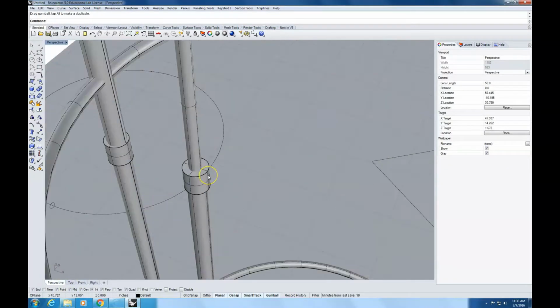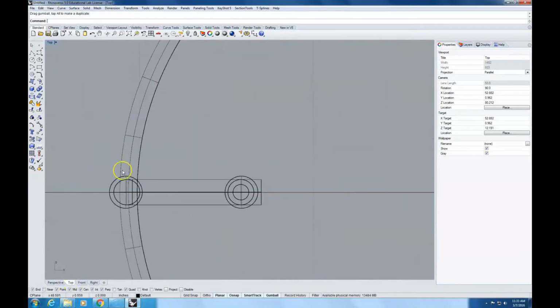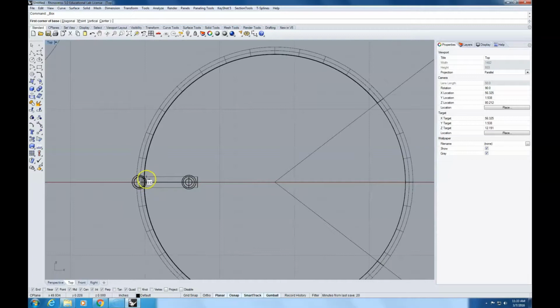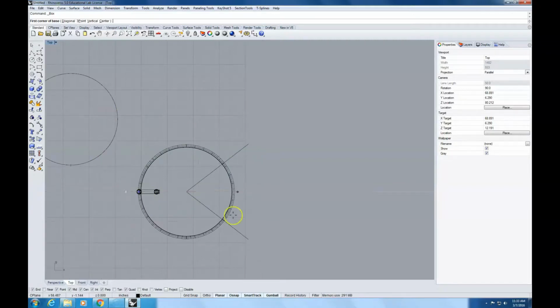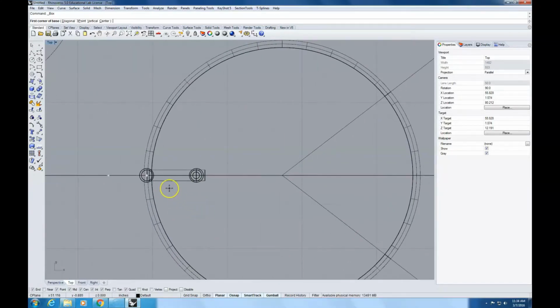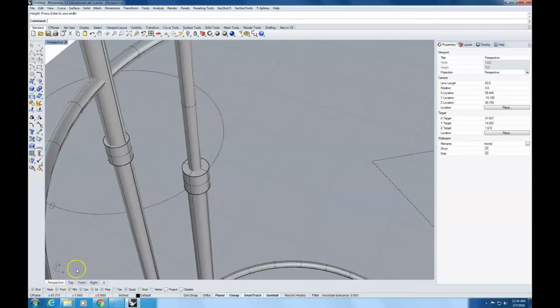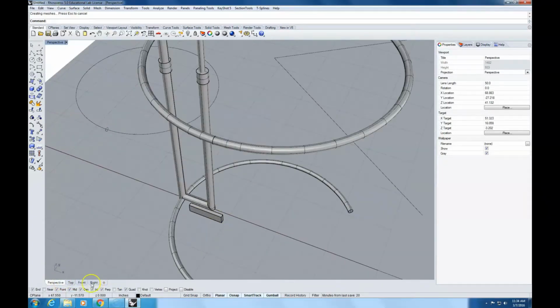Well, there you go. So you're starting to get all these little knuckles and whatever else you guys want to do. I'm just going to go to top view here, create a real quick box. Now, be careful because I have my snap mode on, so it's going to snap to whatever it snaps. So I might be snapping onto the top of this table or the middle of the table, so be careful. By default, if you don't snap to anything, it'll draw on the bottom of the table, if you will, or the construction plane. So in my case, I think I'm just going to eyeball it here because I don't want any surprises, because then I have to move it around and all that other good stuff. So you see how it drew on the bottom of my construction plane.